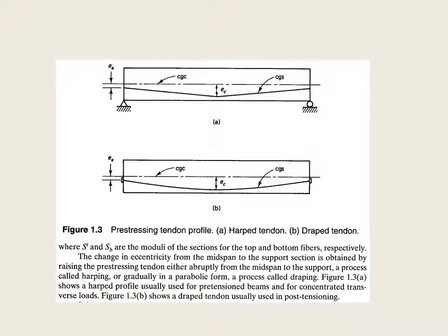Okay, so at the support there is no moment. We call this harping, and this one is draping. Harping is usually for concentrated loads, and this one, draping, is for uniformly distributed load.